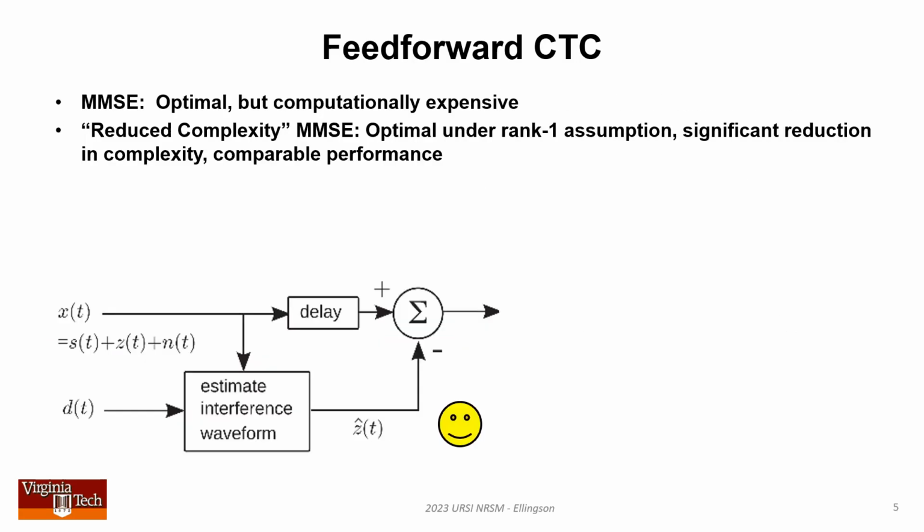So far I've been vague about the algorithms, and that's simply for brevity. The details are in the paper. However, I do feel compelled to say something about the algorithms. Our focus is on a strategy commonly known, at least among signal processing theorists, as MMSE, which stands for minimum mean square error. It's simply a method for calculating a filter which minimizes the mean square error between the filtered reference signal and the input interference.